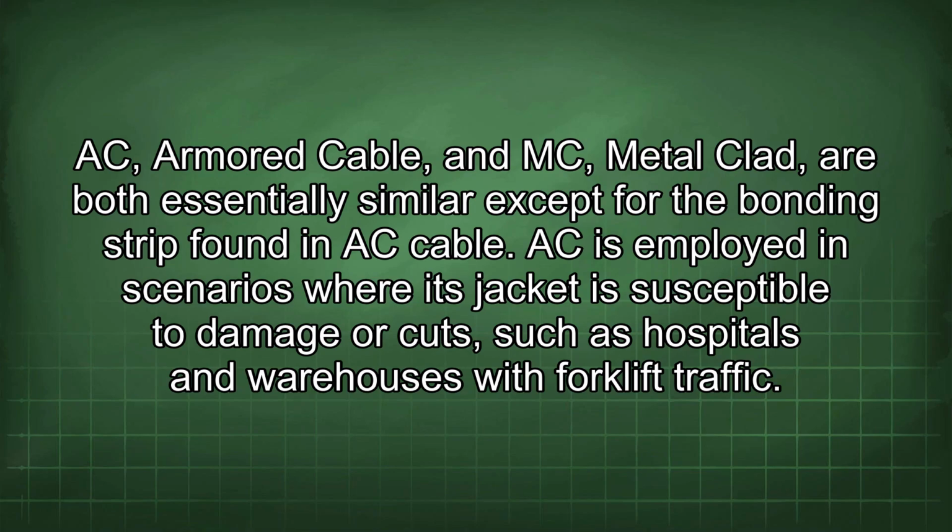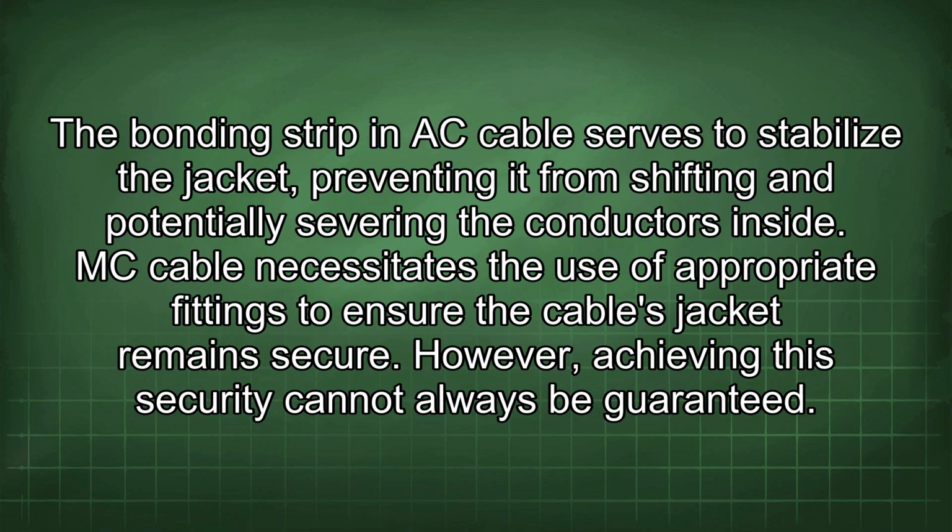AC armored cable and MC metal clad are both essentially similar except for the bonding strip found in AC cable. AC is employed in scenarios where its jacket is susceptible to damage or cuts, such as hospitals and warehouses with forklift traffic.